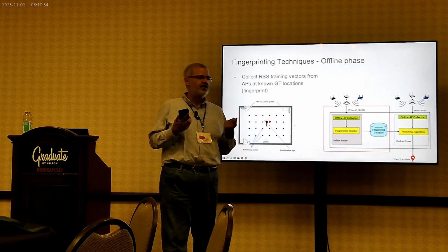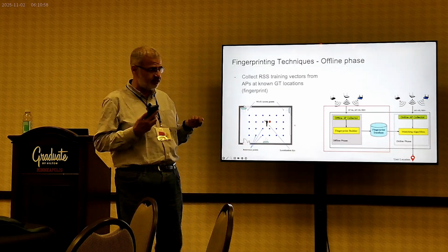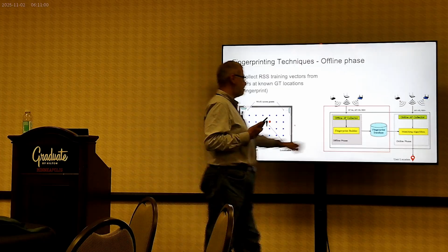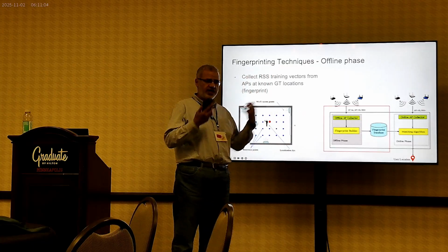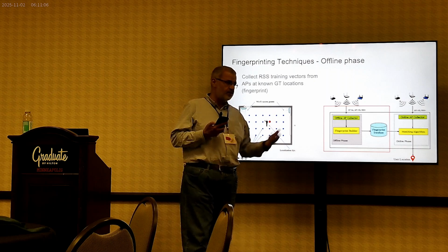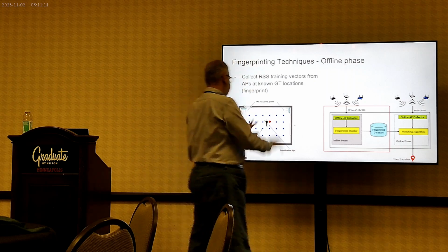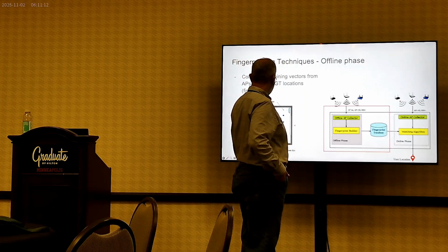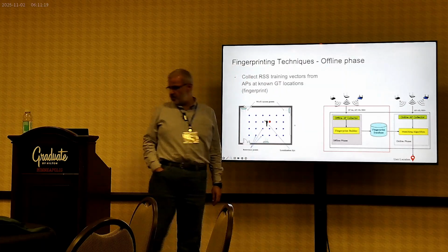So it's like a wireless fingerprint, a fingerprint of the wireless signal. And I store this in the fingerprint database, and then I move to another location, collect the signals, and so on. So this is a calibration phase that I do once. And after this calibration phase, I have for each one of these locations the signature of the different access points, and this is what we store in the fingerprints.